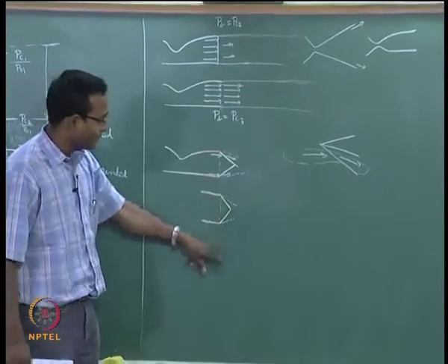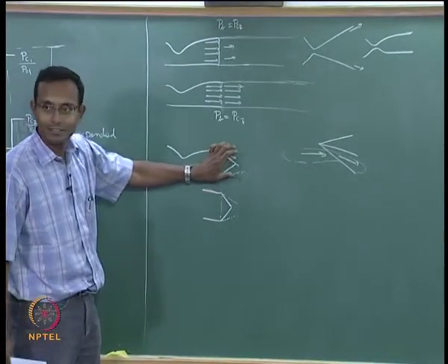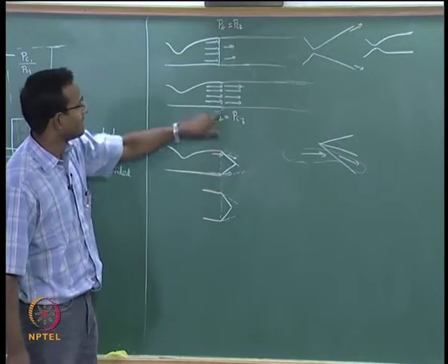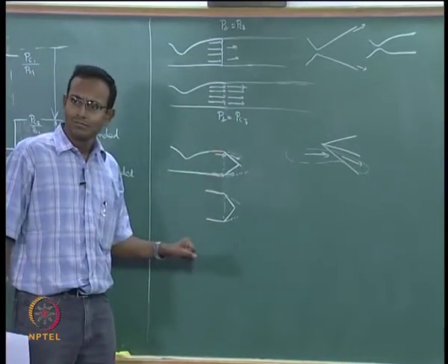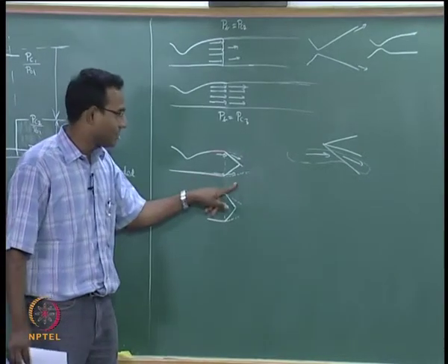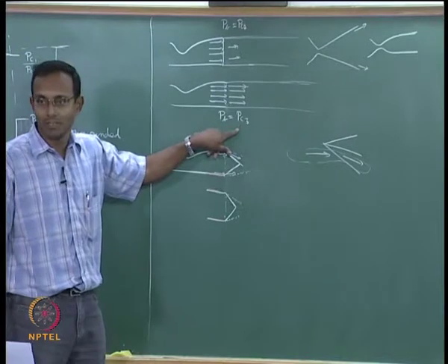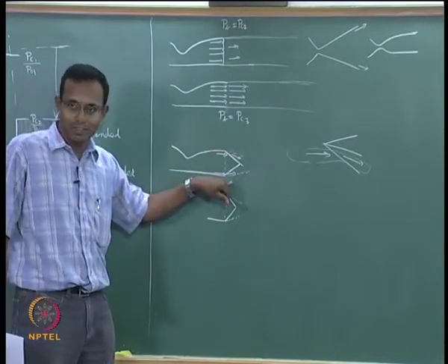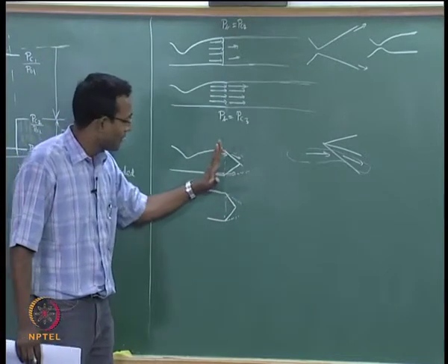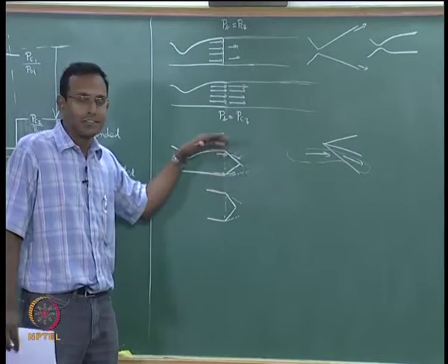and then when I decrease further it goes to this case where it is slightly expanding, and eventually it will reach this case. How does it reach this case from here? I keep on decreasing my back pressure, it is going to tend to PC3 eventually. Back pressure is some value here, I decrease back pressure, what should happen here? My oblique shock should be at less angle, beta will decrease, okay.